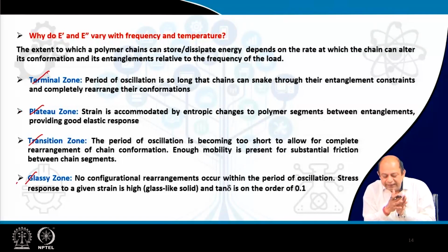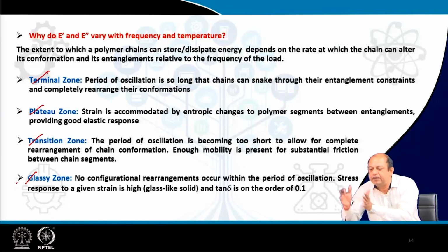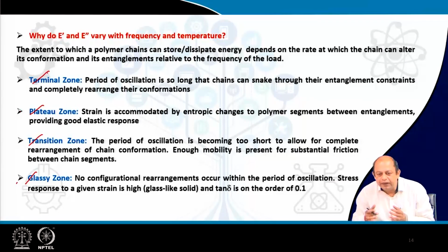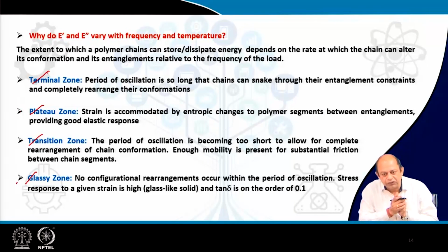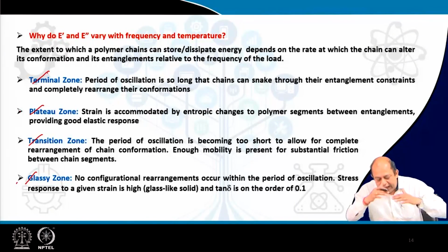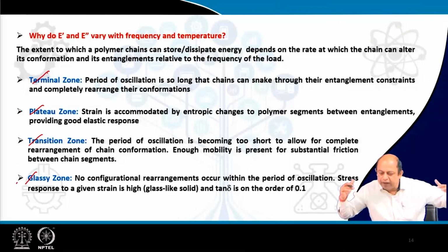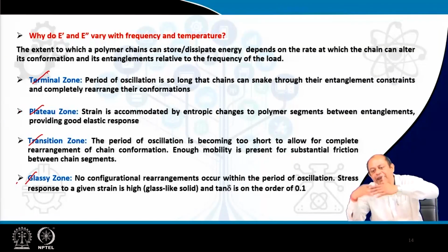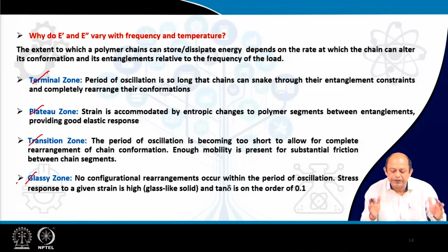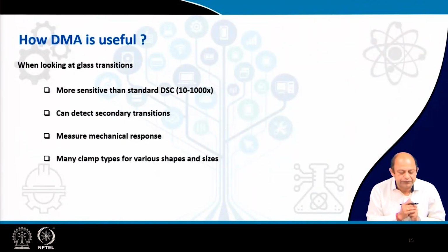And then in the rubbery plateau, what happens, it does not really matter whether there are 20 or 40 such segments giving you a cooperative movement. This cooperative movement will be all throughout the chains, and modulus remains almost constant there. So, storage becomes constant, and it tries to dominate the loss modulus. Loss modulus will be lower there. But at a certain point of time, this movement is so rapid across the chain, they will try to go past each other, slip past. It flows basically, and then again loss tries to dominate. Every depiction is given here, and you will be given that particular part subsequently.